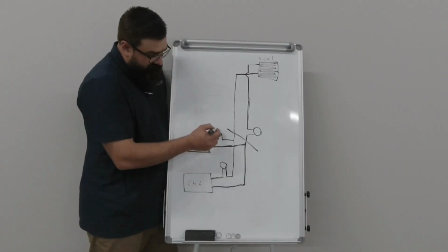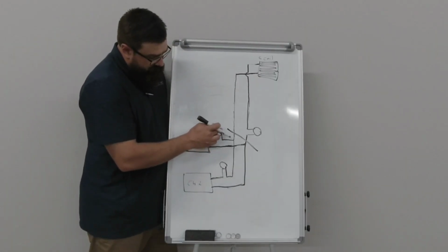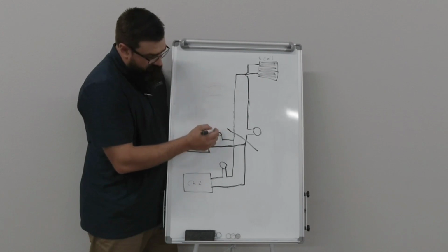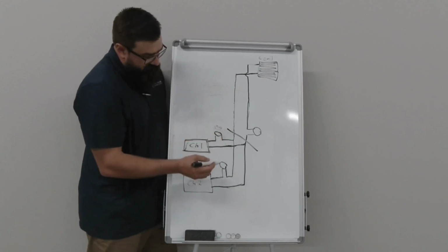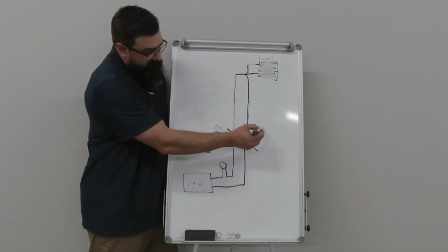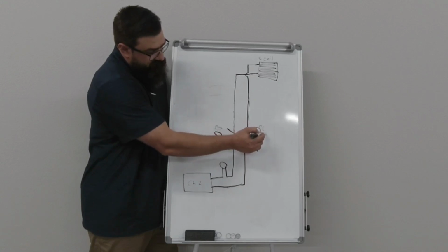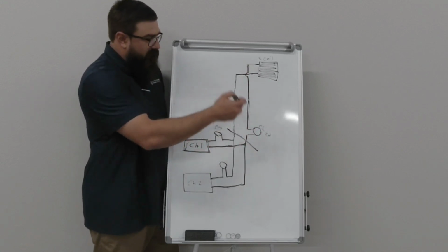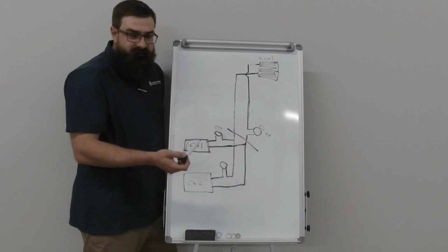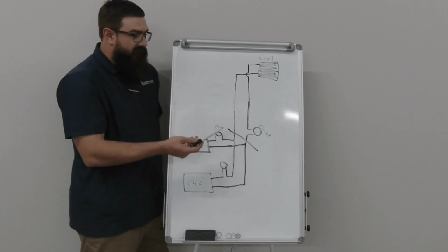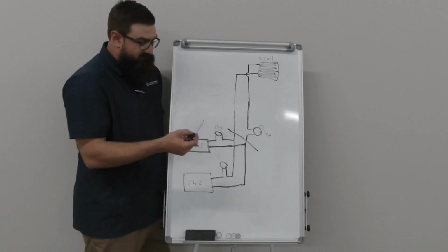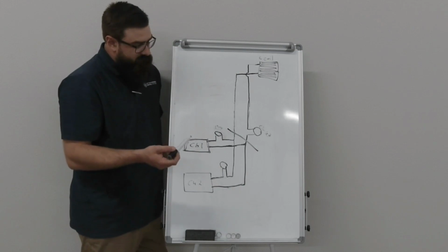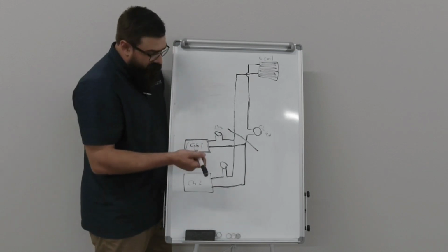These stay constant volume. So they're always running at whatever, let's just say 100%. And then this can actually modulate to go from 0 to 100 to maintain whatever the building is looking for, whether it's set for GPMs through the entire building, or if it's set for pressure control. It can be either way.